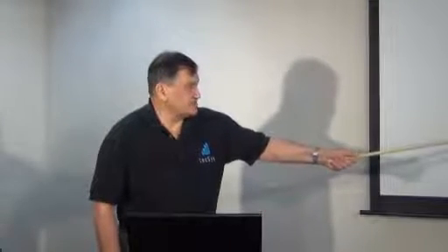And remember, we went through that whole process: to raise the high side voltage, you normally raise the high side tap. To raise the low side voltage, you normally raise the low side tap. That's the conventional approach of doing it. So again, these numbers are there to specify the regulating band. We can have a number of tap positions. We can have a step size.